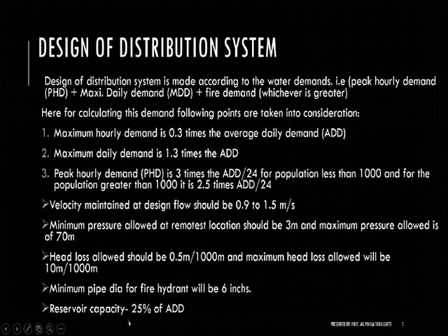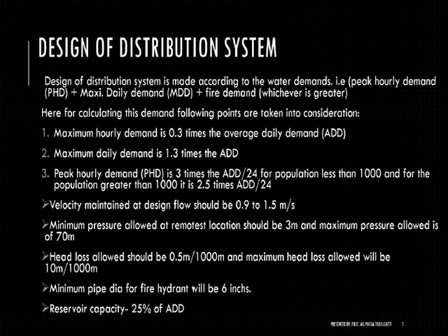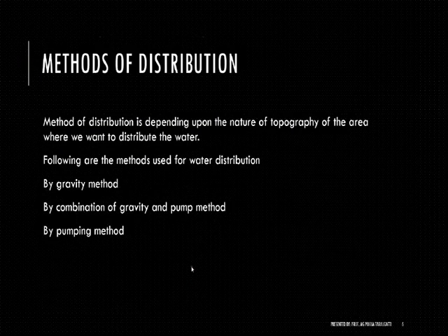Reservoir capacity is 25% of your average daily demand. You need to maintain your reservoir capacity at 25% of the average daily demand. Okay, so here we have covered what the design will be. In the next lecture, we are going to cover methods of distribution system.